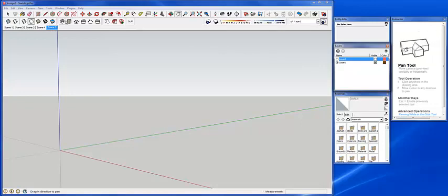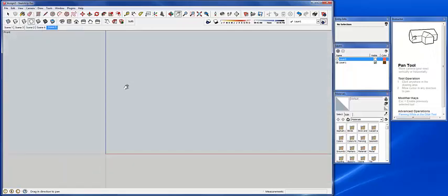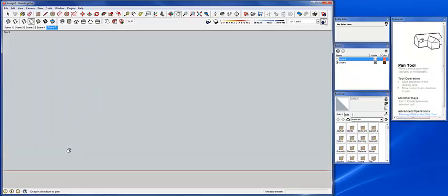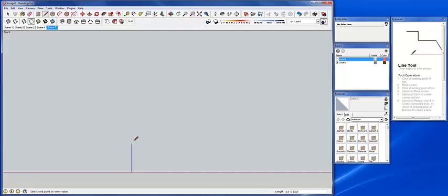We'll go ahead and set our view to elevation here, and we're going to set our camera to parallel projection. All right, and you can see now we're looking at this in elevation. I'm going to zoom out, and so that I don't double up on the space here, I'm just going to go ahead and draw this. So using the line tool, or L, I'm going to go ahead and start drawing. And if you look at the drawings, the initial part of the construction there is 8 feet tall, so I'm just going to type that in, hit enter. And you can see that if you're paying attention down here, we'll update the second leg of that. Then it's going to start to pitch over for the roof. The roof on center is 12 feet, so I'm going to go ahead and type that in as well. And then it goes up 13 feet tall.